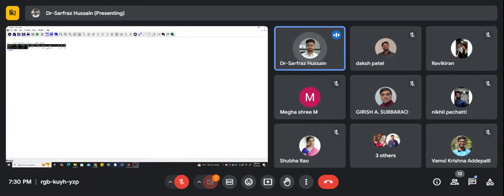Now when you see the NMOS and PMOS, the connections are already there, right? Output, input, VSS, VDD. All these connections are already given: drain, gate, source, bulk. Like that for NMOS and PMOS, both are given. Now we need to call upon the model files for the NMOS and PMOS. So how do we call upon them? For that, we can write .lib. Okay, so we can include the library file, .lib and the location of the file.